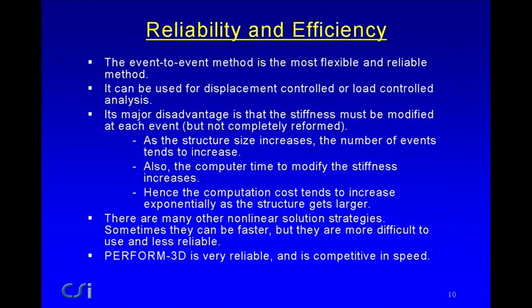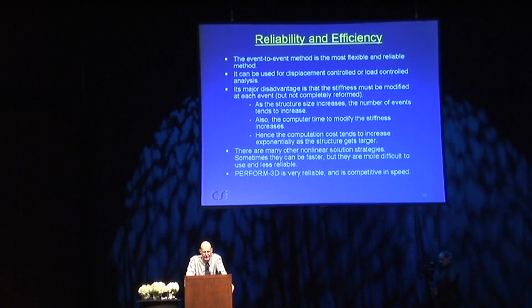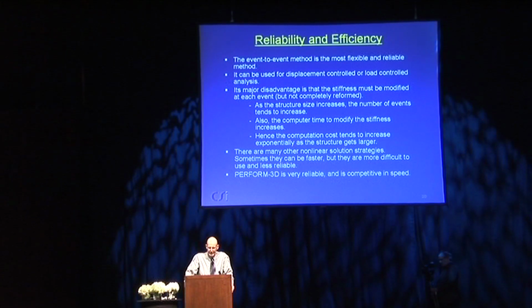Nevertheless, although there are a number of other strategies, and sometimes they can be faster, my experience has been that they're more difficult to use and less reliable. And I think even given the disadvantages of the event-to-event method, it still is the best method. And Perform 3D, I think, has proven to be very reliable, and it is competitive in speed. I'll show later on, if you've got some monster structure, it can take a long time to analyze, you have to admit that. But most structures of reasonable size don't take an outrageous amount of time. And as computers get faster and faster, we'd hope that the analysis times will get less and less.